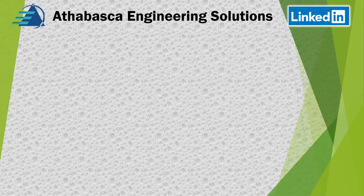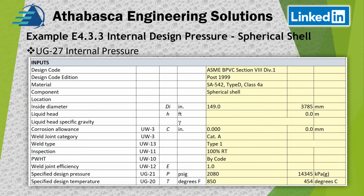As per usual, we set up our table, and we have our values shown here. This material is more typical of spheres, so we use that. You can see the diameter, it's not a huge sphere, but it's 149-inch ID, and in this case there's no corrosion allowance. Because that's probably a gas, the joint efficiency is 1, and the pressure is 2080 psi, and it's quite hot. We're at 850 Fahrenheit.